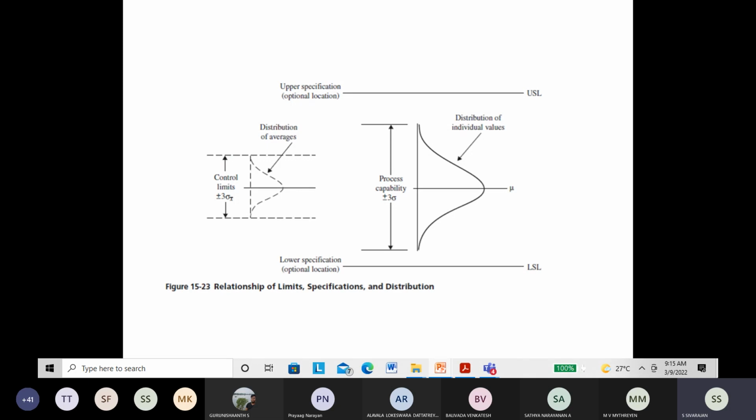That is why, if you keep a tolerance, some type of variation is acceptable because the cost is very less. Instead of going for a very high-end CNC machine, we can go for an ordinary CNC machine where the precision levels are a bit low, because the cost will come down. Even cutting tool cost and equipment cost will come down. So that is why sometimes it is acceptable. That is called specification. Some type of variation is permissible.